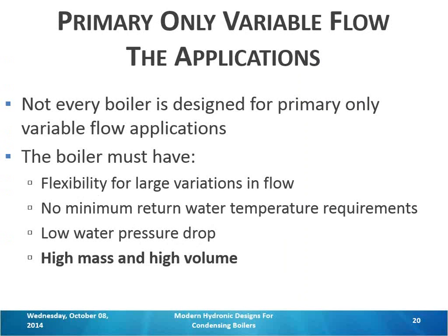So what are some advantages of high volume? Well, you're less resistant to things like erosion, scaling, changes in flow. If you think about a big tank, like a residential water heater, that doesn't need any flow to operate. That's because it's just a big tank. It's going to heat up the temperature and it's going to turn off. So the more water that you have in a boiler, the better able that boiler is to tolerate low flow conditions or even no flow conditions on some boilers.